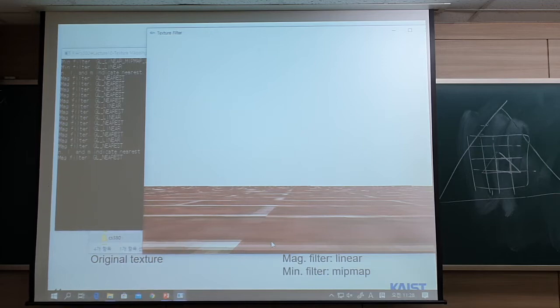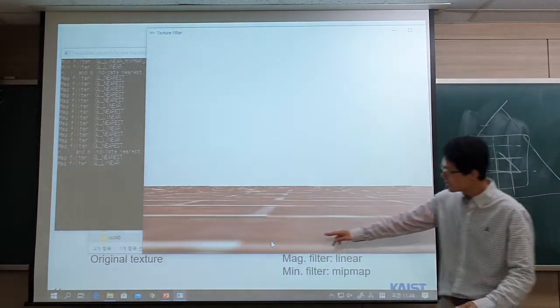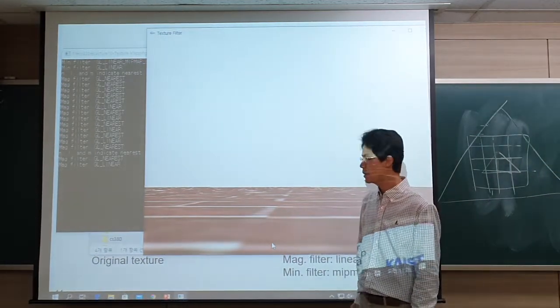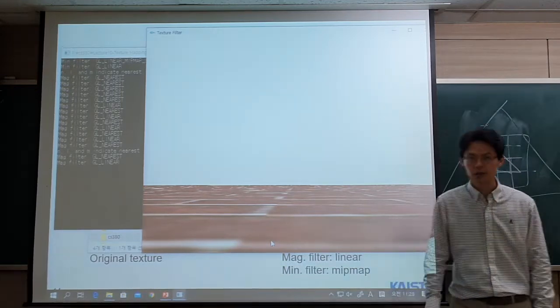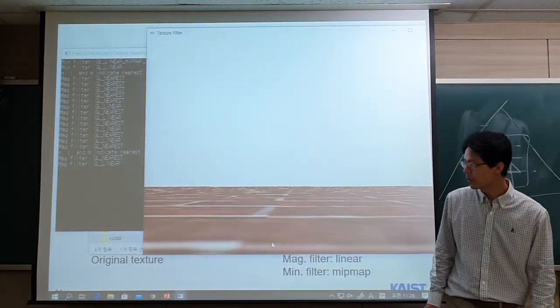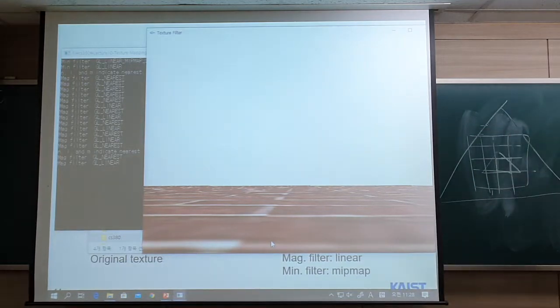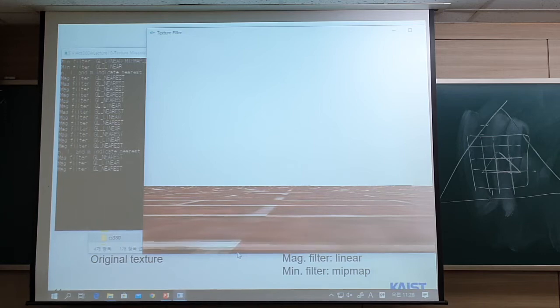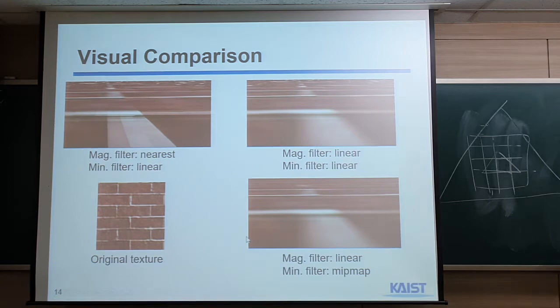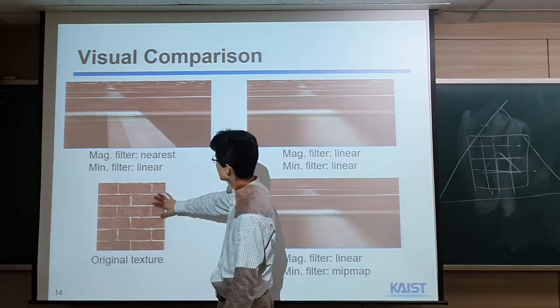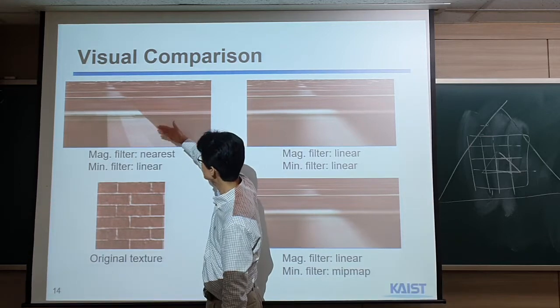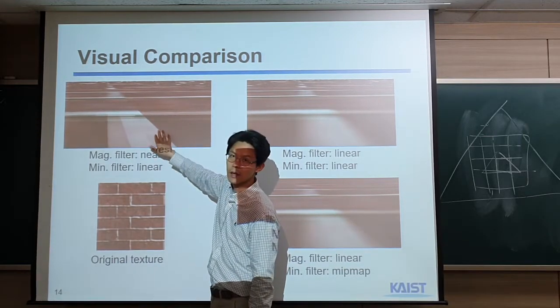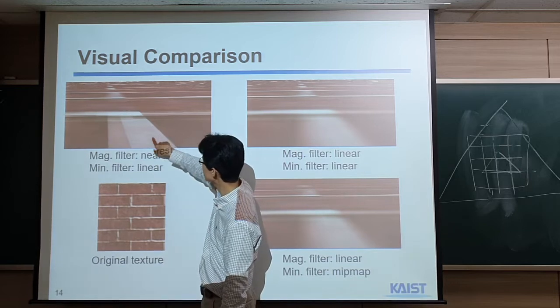And then if I choose the linear, in other words, like bilinear, then you can see that the pixel color changes smoothly, right? That's the main benefit of using this bilinear interpolation. So it looks better, right? It looks more smooth. When I change it, you can see that, right? In this case, the original texture is like this. It's very low resolution, and again, when you zoom in this triangle a lot, you can see that an oversampling issue happens. You can see this texture boundary.